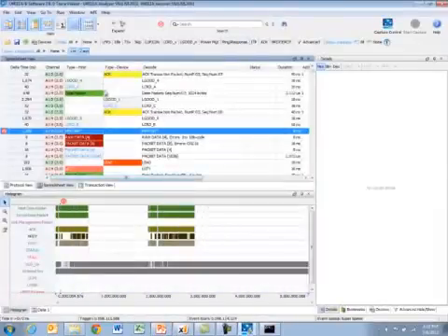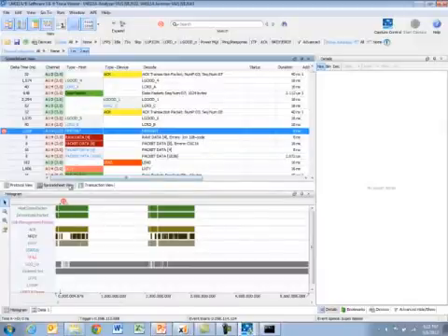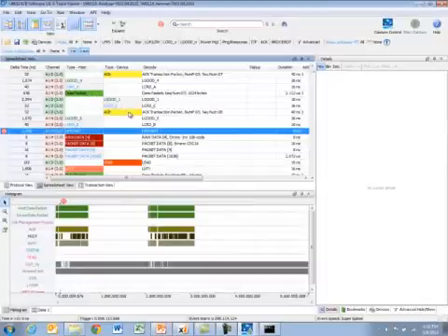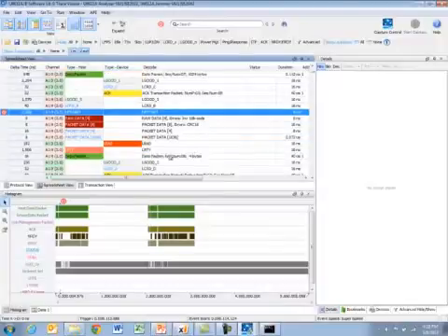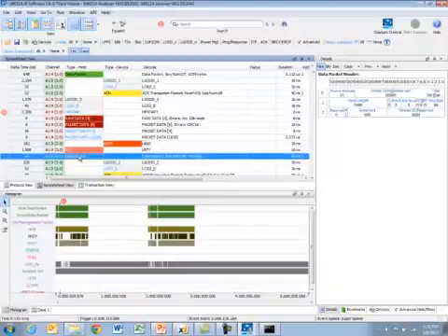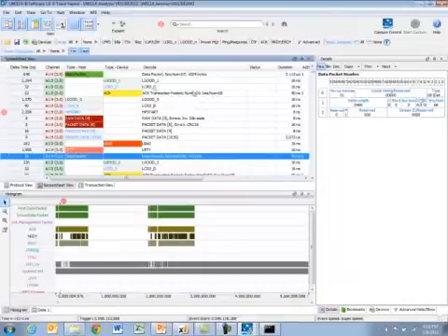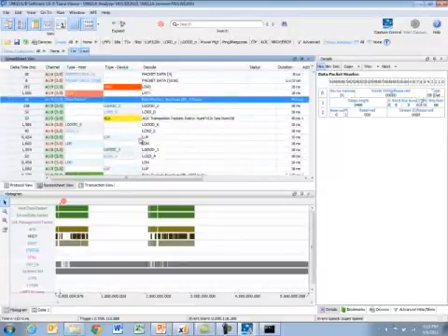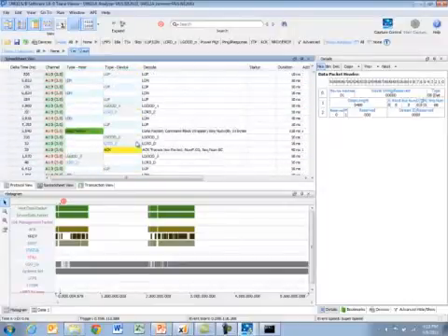And what I see is that it immediately takes me into the link where I triggered. Data packet, acknowledgement. The next data packet, header packet start, there was a 10-bit code error in that data packet. Also caused a CRC error, not surprising. My device responded back with a link bad. Host said, let's retry. And it sent the data packet again. So here it was sequence number 7, corrupted, sequence 8, and the communication kept right on flowing along.